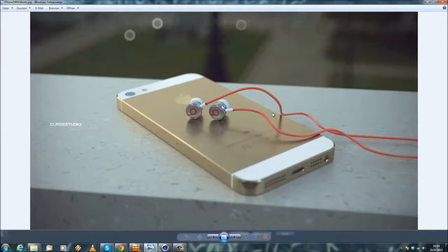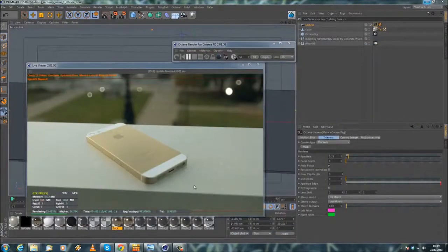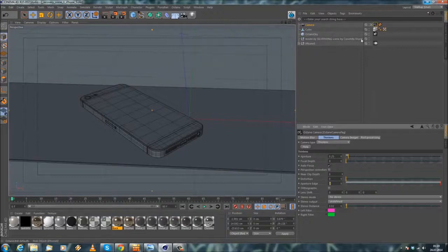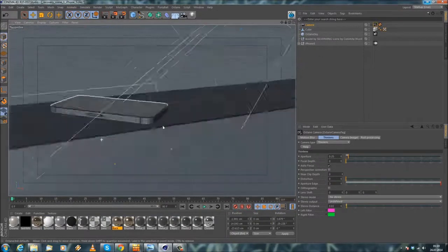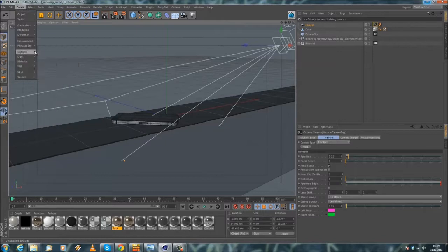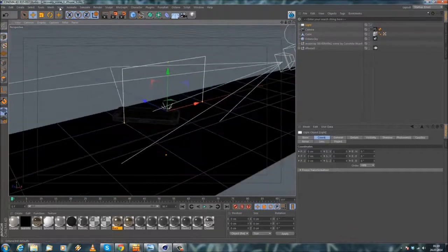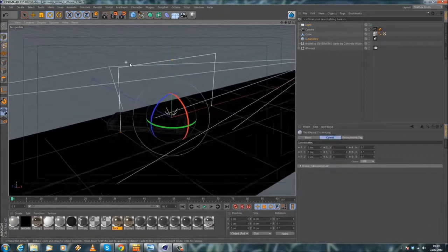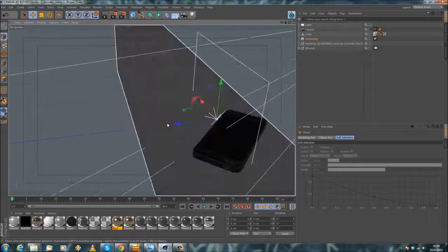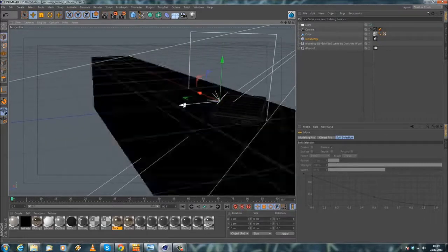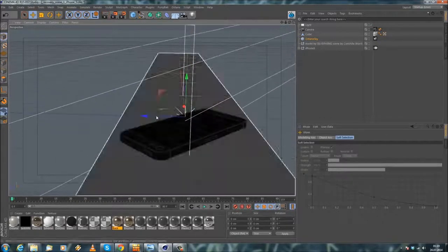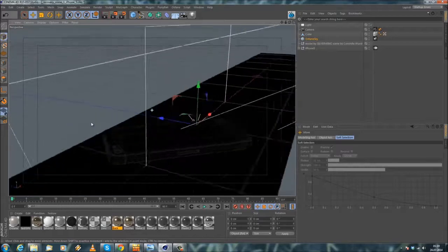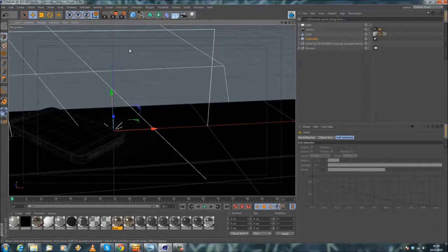So that's pretty good. The problem here is that we don't have anything reflecting here, which is not really good. So what we can do about it is simply mix an area light with this HDRI that we already have in the scene. So we just go Light, Area Light. By the way, the light always shines in the Z direction. So wherever the Z axis is with this area light, there you will also have your light shining. In this case, it's pointing in this direction.